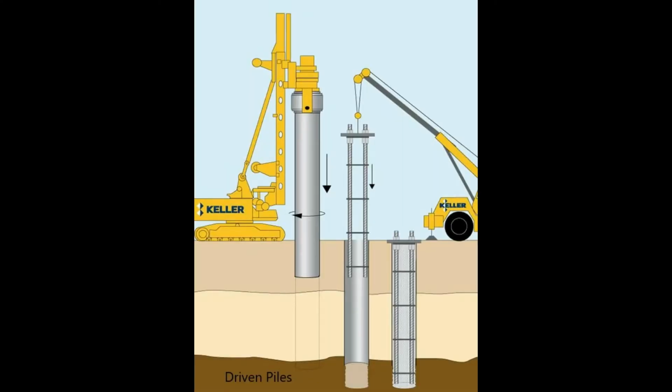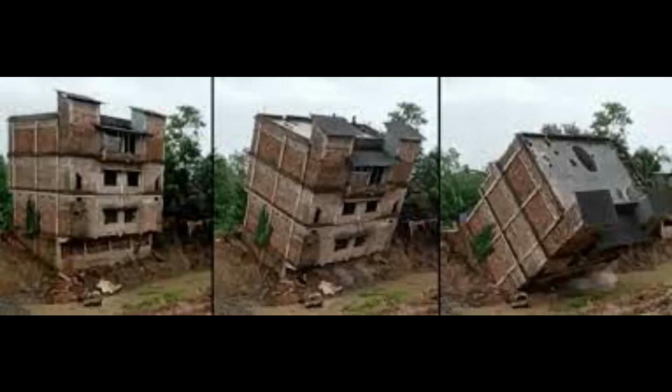Peat soil is commonly thought to be unsuitable for supporting foundations or loads in its natural state. When peat soil is subjected to even moderate load increases, it is prone to instability such as localized sinking and slip failure, as well as major and long-term settlement.